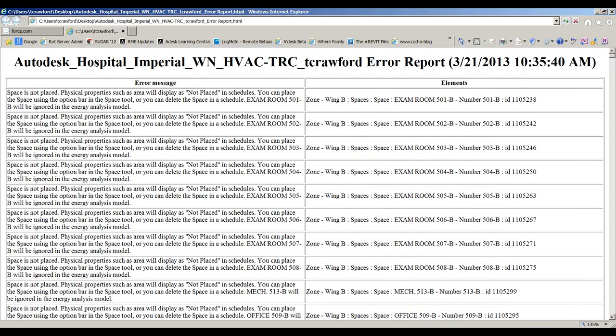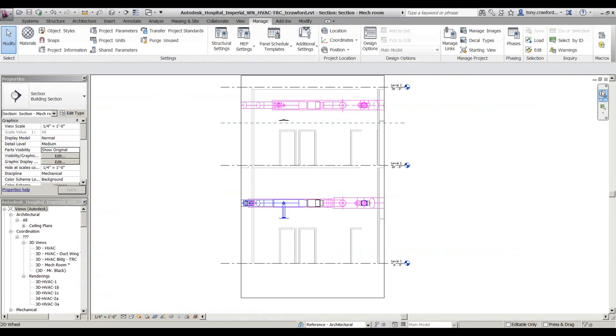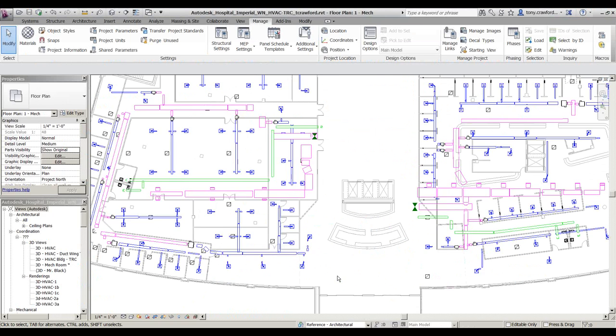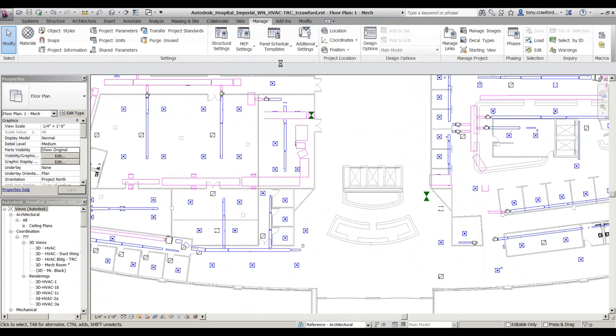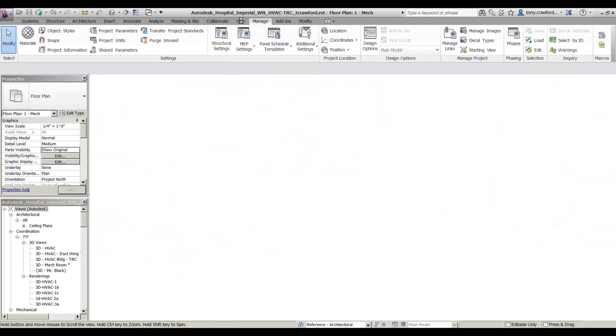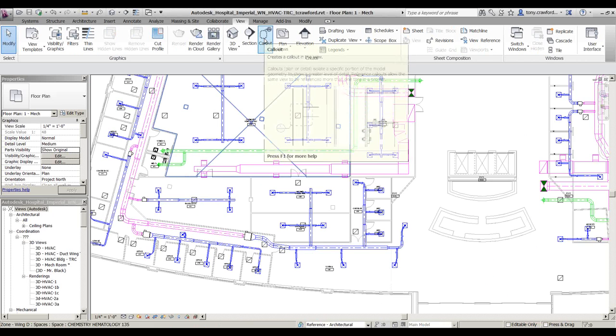If I have a big floor plan, and for a week I'm going to work in a specific department or a specific area, what I recommend doing is, let's say Tony's going to work on the left side of the building. I will go to my callouts and make a working view for that left side of the building. I'll make a callout for the left side, and that'll be a working view. And then when I come back later,